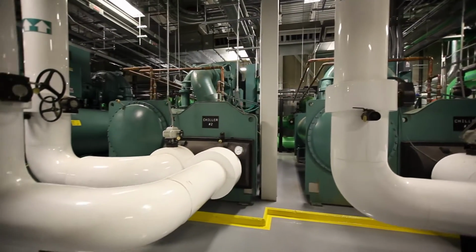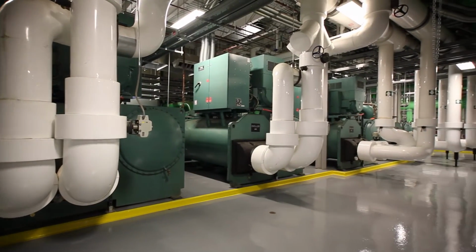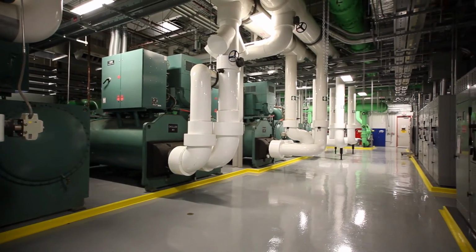A principal improvement in the efficiency is due to the absence of compressor power. If you were to compare this facility with a traditional data center using chillers, CRAC units and chilled water pumps, and compared the energy profiles, you'd see that the biggest user of energy besides the IT power is the cooling power, and a big chunk of that is down to the compressors that serve the chillers. Well, in this facility, we don't have any compressors, we don't have any refrigerant. The only energy that we're using to cool the data center is the fan power associated with the indirect air cooling units and the water pumps that supply the water for the evaporative cooling.